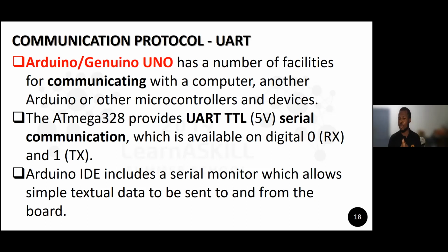Something causes a voltage drop, and the Arduino is unable to listen to the communication from your USB port. From what I've seen, anytime I have done that previously, my USB doesn't connect to the Arduino, or I'm unable to load code unless I remove the Arduino from the circuit. Since I detected that some years ago, I never use my UART pins, the RX and TX, for anything. Even when I need more pins, I make sure I don't touch them.